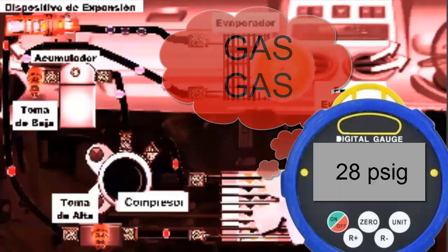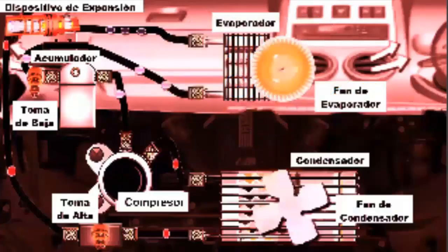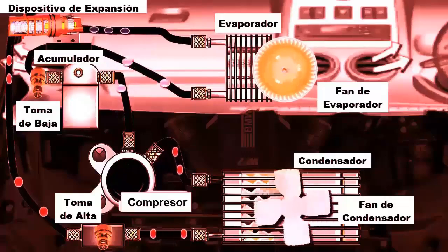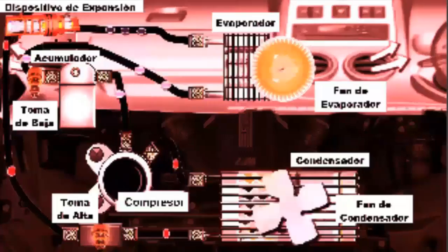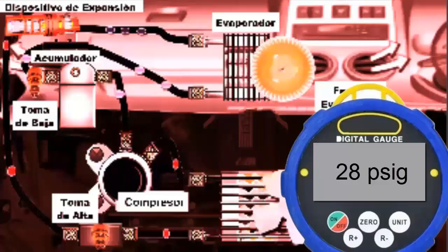Another situation where the low-pressure switch deactivates the compressor is during high vehicle acceleration. In such moments, an instantaneous drop in pressure occurs, temporarily deactivating the compressor. This allows the vehicle's engine to focus its full power on acceleration rather than cooling.